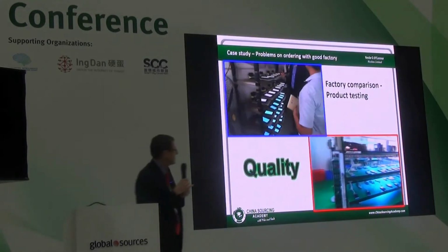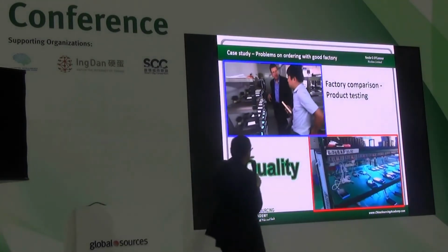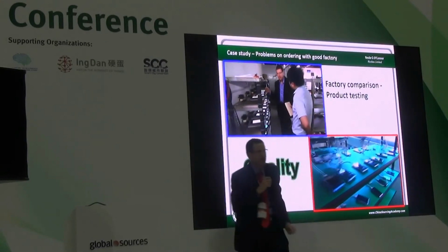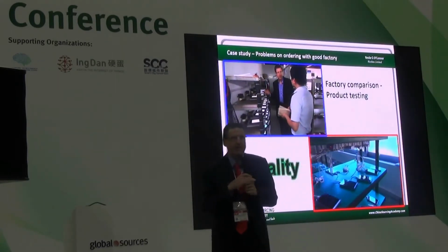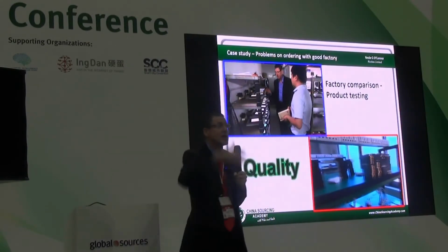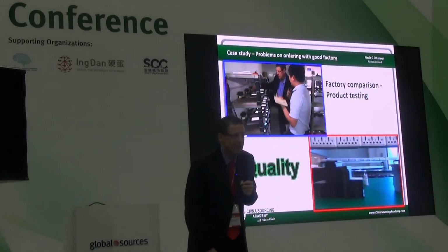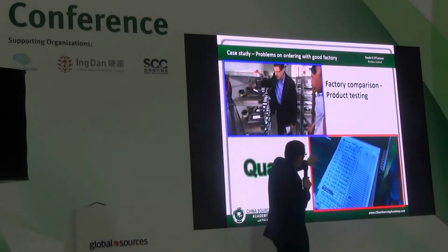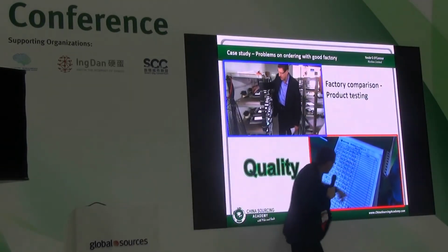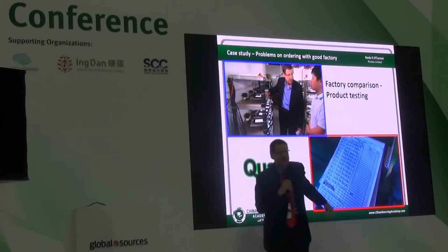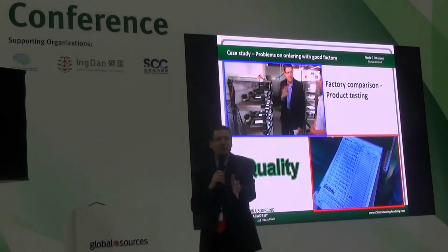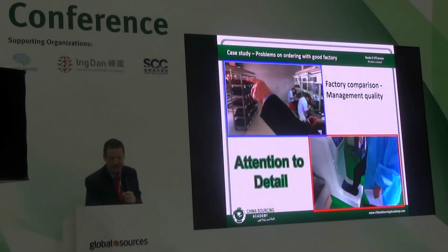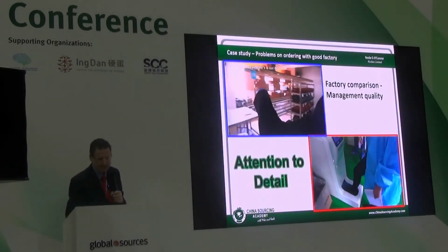When you're in electronics, you need a burn-in room. So for 4 hours, 8 hours, all the units, 100% of whatever's made is turned on. They want to test the battery. Then they'll drain the battery. They should actually charge it up again. Not many of them do that, but there's a process here that needs to be taken care of. And what you're looking for is actually a documentation of that process. So you see the process, are they documenting it? That's critical, critical, critical.